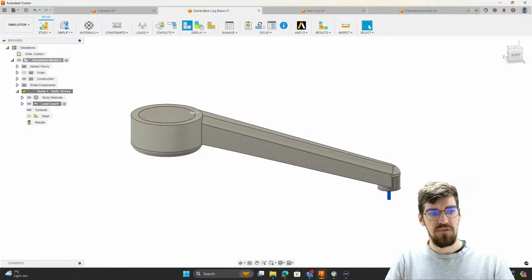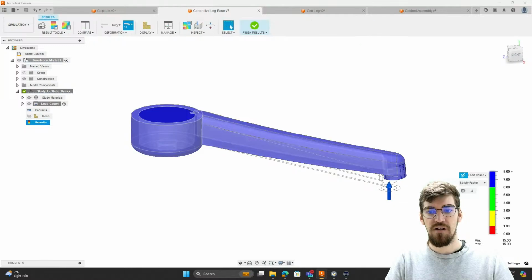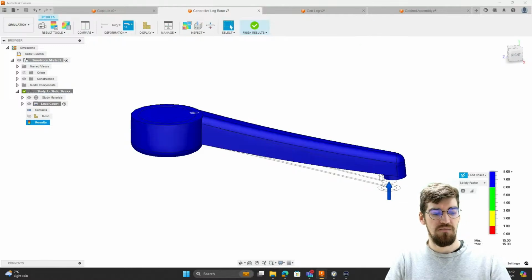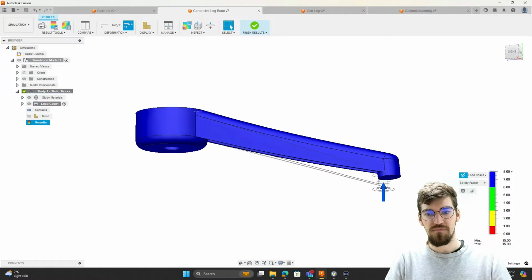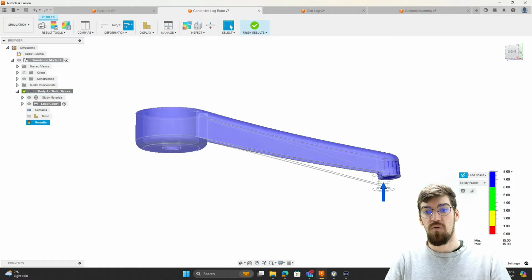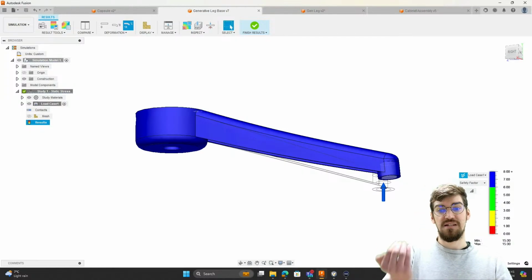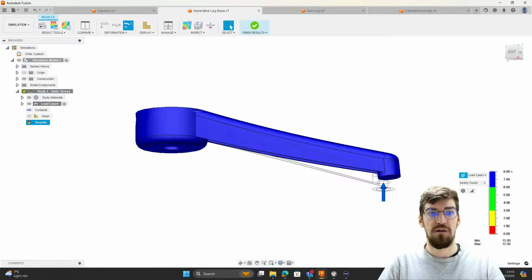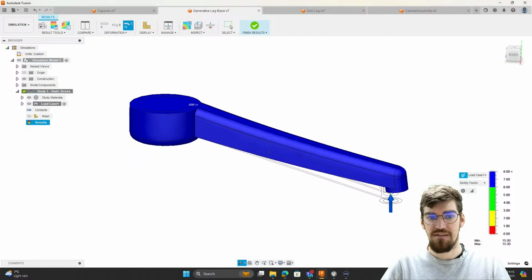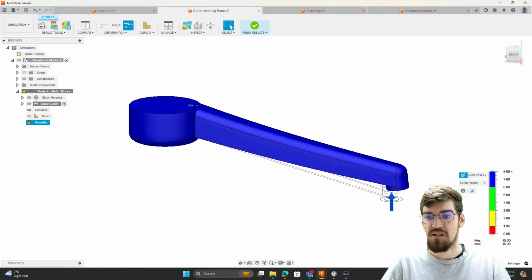So we've got the load case all set up, and the results are in. I'll just go into the result itself, and I can see that our force is applied against that wheel connector, and we can see that force is actually pushing the component up ever so slightly. Now this is a slightly exaggerated version of it, just so we can see the force itself. But what I can see from here is I've got more than 8 times safety factor. So this is more than 8 times stronger than we really require for the sake of passing this particular component.